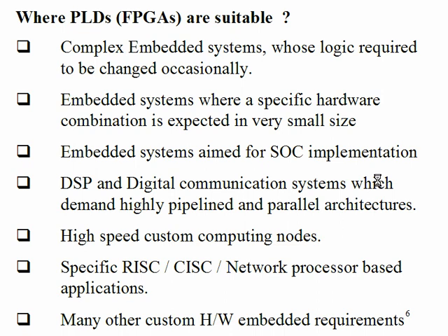See, when we talk about toys, we aim at a market of millions, or at least a few lakhs of pieces. But when you talk about an onboard missile controller, will you talk in millions? No. After all, I may have a requirement of 500 missiles or 1000 missiles, or when I talk about the aircraft controller, onboard aircraft, I may require in hundreds. So on one side, once you talk about a complex embedded system, it becomes very complex. Because it's very complex, once you want to do it at the silicon level, ASIC becomes costly. On the other side, complex embedded systems generally we require less in number. Got the point? Because of both these reasons, we generally go for FPGA based solutions.